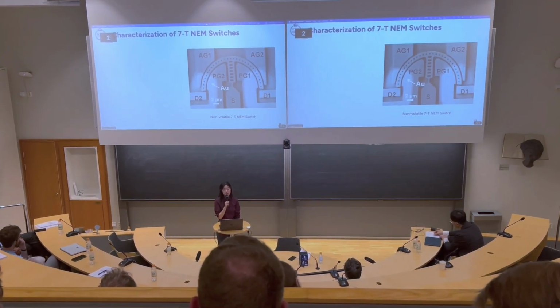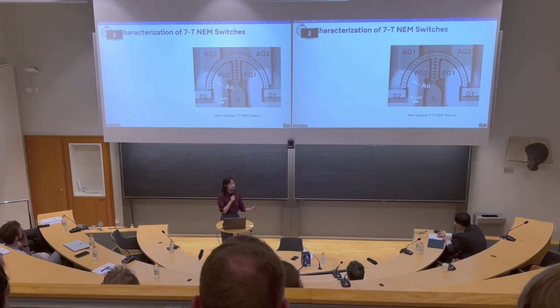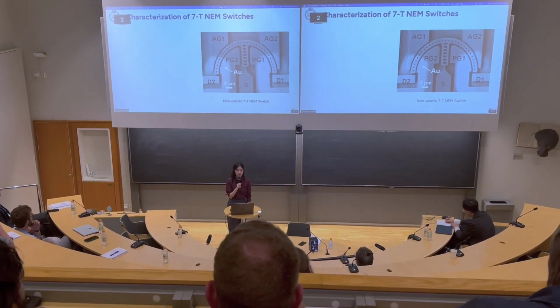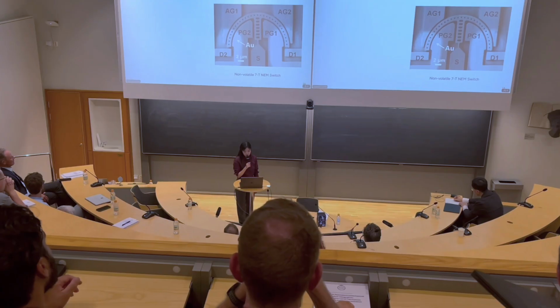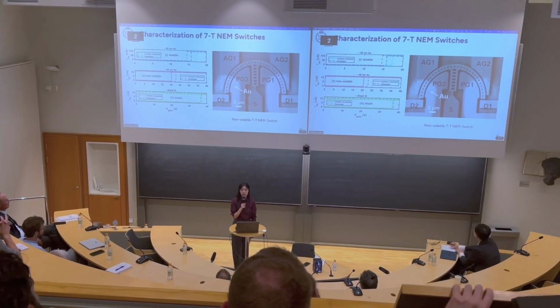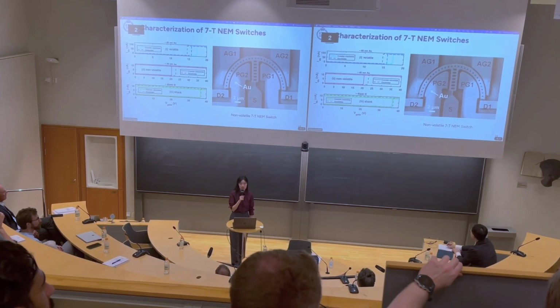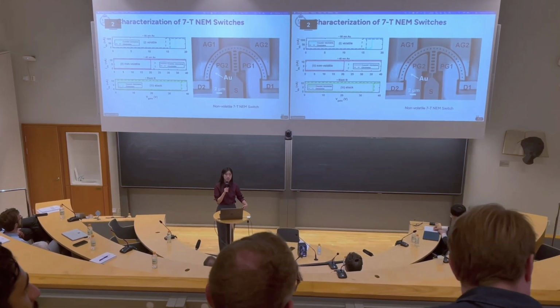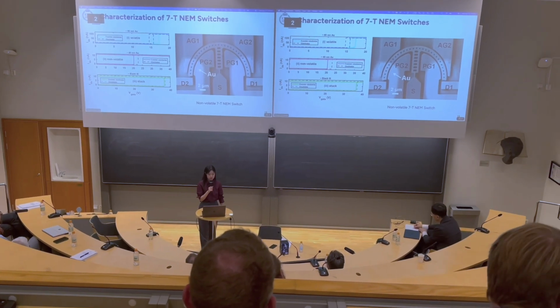And for the 17 NEM switch, we also characterize it by grounding the source terminal, and then we put a bias voltage on both drain terminals. For this configuration, we investigated 3 different groups: blank silicon contact, 80 nanometers of gold metallization, and 40 nanometers of gold.